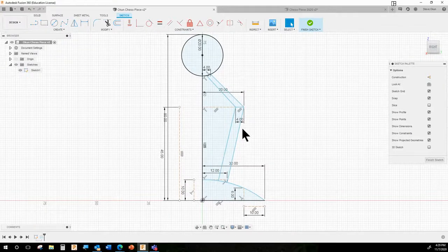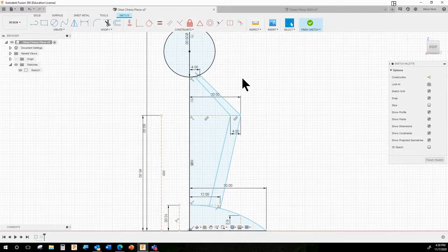Okay, so now I want to make these two lines parallel, and I want to make these two lines parallel. But I don't want these two lines to move, because these two lines are right. If these two lines are not parallel, they're the ones that are wrong. These two lines I drew to my client's exact specifications, 20 millimeters out, 45 millimeters high. So these two are right. They're fixed to reference points. These two are the ones that, I didn't make a reference point for here and here because I have parallel constraints. I don't have to do that. You'll see, it's a really cool thing.